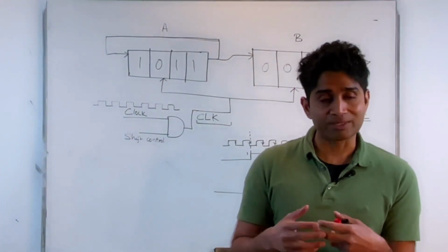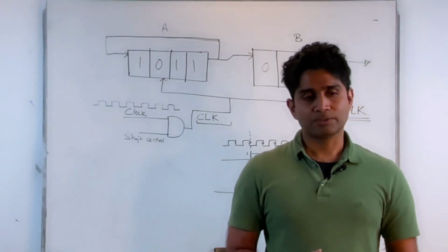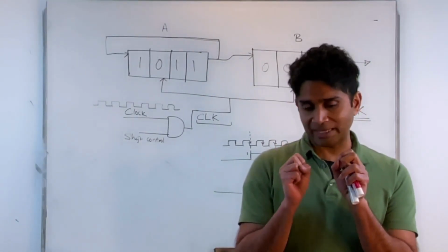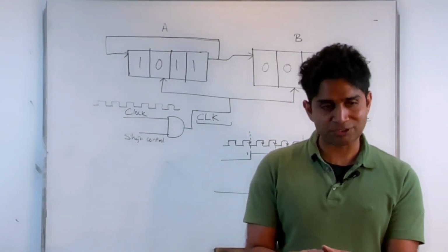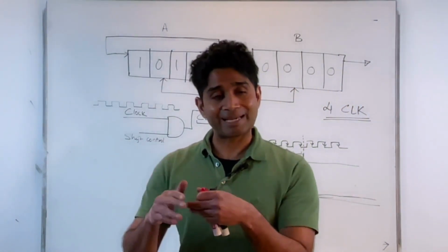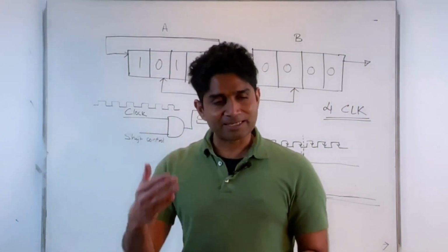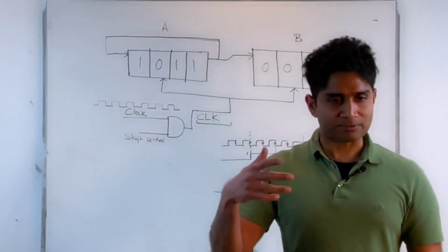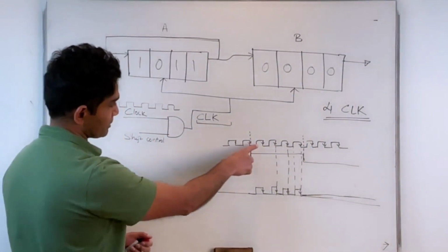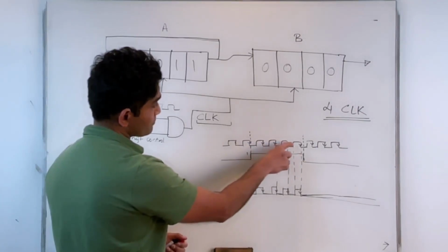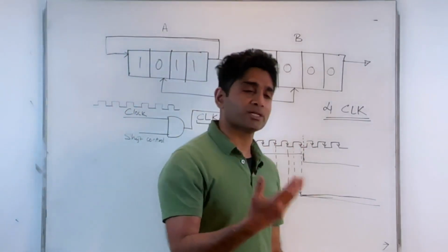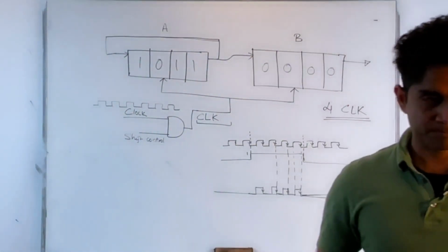So it depends on how you design your flip-flop. If you design it as a flip-flop that gets triggered on the negative edges, then it's called a negative edge triggered flip-flop, and it gets triggered only on the negative edges. So it does not see the positive edges. For example, here, these are my positive edges, and my flip-flop does not get triggered during those positive edges.